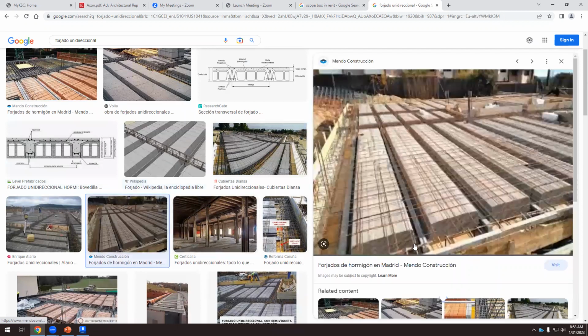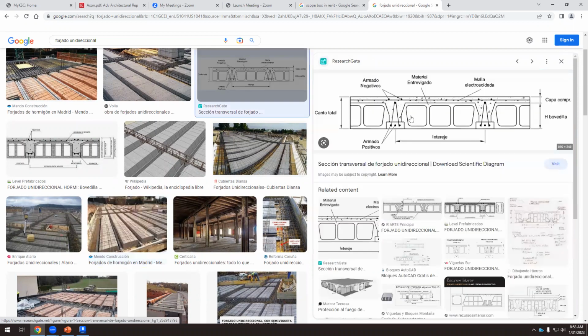So why are we using this? Because the concrete is so heavy that if we cast a lot of concrete, the construction will end up being too heavy. So we don't need that. Okay, so we can have the beam, then the joists, and then these vaults that are hollow. They are not solid, and they are lighter. As you can see, it's not a solid element. The resistant element is the joist itself. This is not resisting, it's just covering the span between two joists, which can be around 2 feet, something like that.